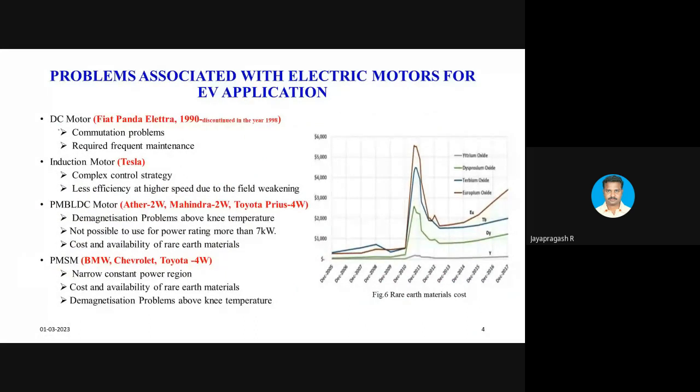See, if we consider DC motor, right? So we know that DC motor is a parent motor. Even now, if any researcher is introducing a speed control technique in the market, the quality is cross verified with the speed control characteristics of the DC motor. Generally, it's a practice, even if you consider vector control or direct torque control, always we will be trying to operate an induction machine just like a DC machine, so that its characteristics exhibit the characteristics of a DC machine. That way only we will be developing speed control algorithms for an induction motor.